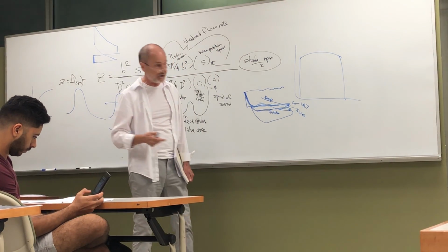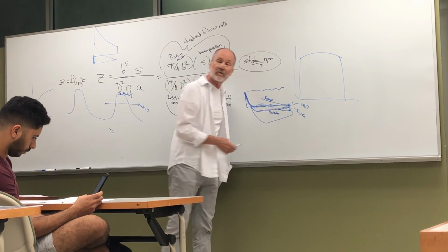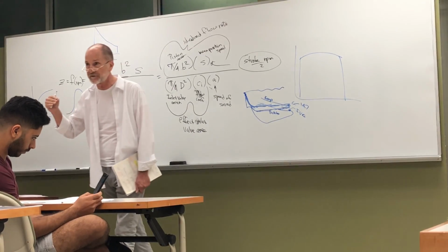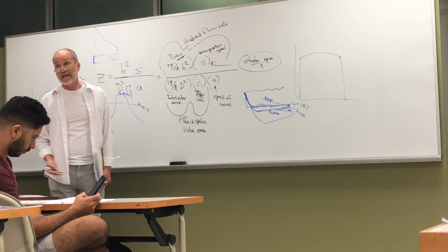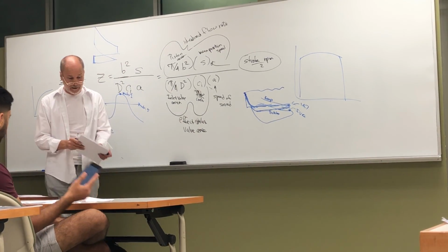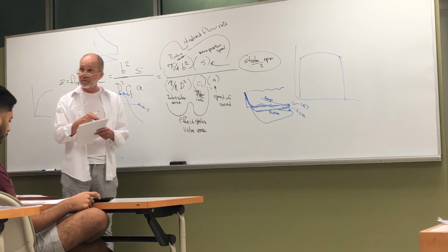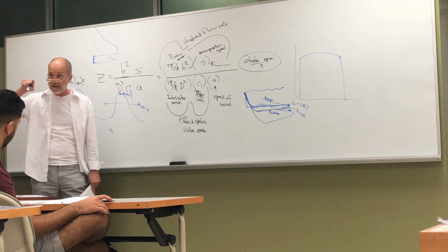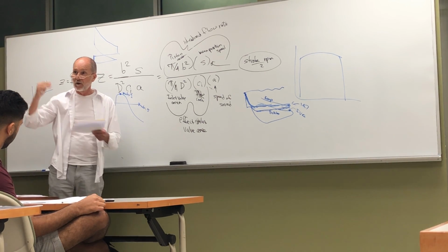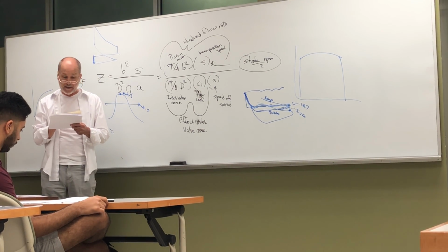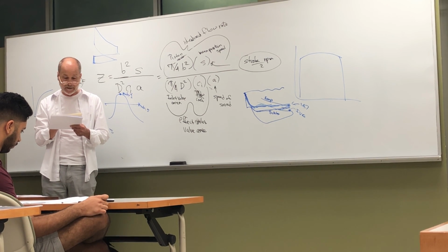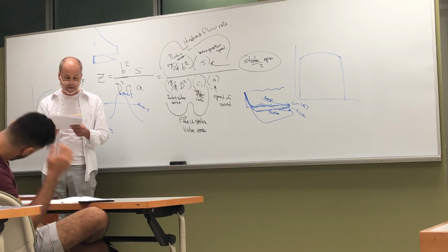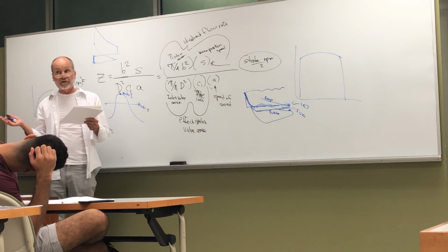By Mach index 0.6, we're not quite reaching back, and we're beginning to experience a drop in volumetric efficiency. At Mach index 0.8, of course, it's a big drop. You can see that best at wide open throttle, from where the pumping loop turns around from the intake and starts the compression. At what pressure is that occurring? As you go to higher and higher Mach numbers, it occurs at a lower and lower pressure. In the case of Mach index 0.8, it's down close to 10 psi.